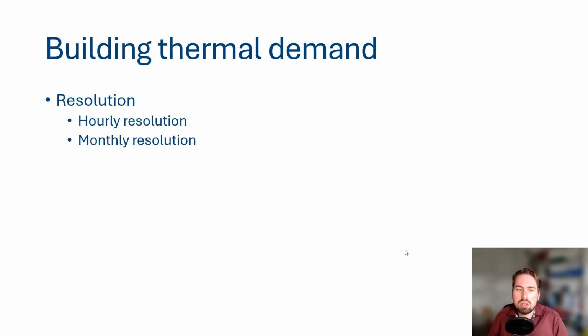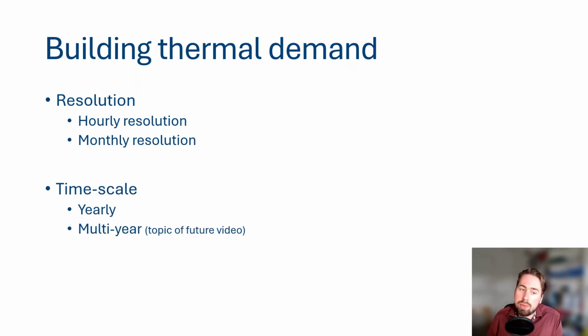So within GHEtool, you can enter the thermal demand in two resolutions, let's say. You have either hourly resolution or you have a monthly resolution. And you even have the option to do it on a yearly or a multi-year timescale. Now, what we mean by that is that typically you enter your hourly load or your monthly load for one particular year, and you assume that for the whole simulation period, this energy profile just repeats itself. This is what we call the traditional yearly